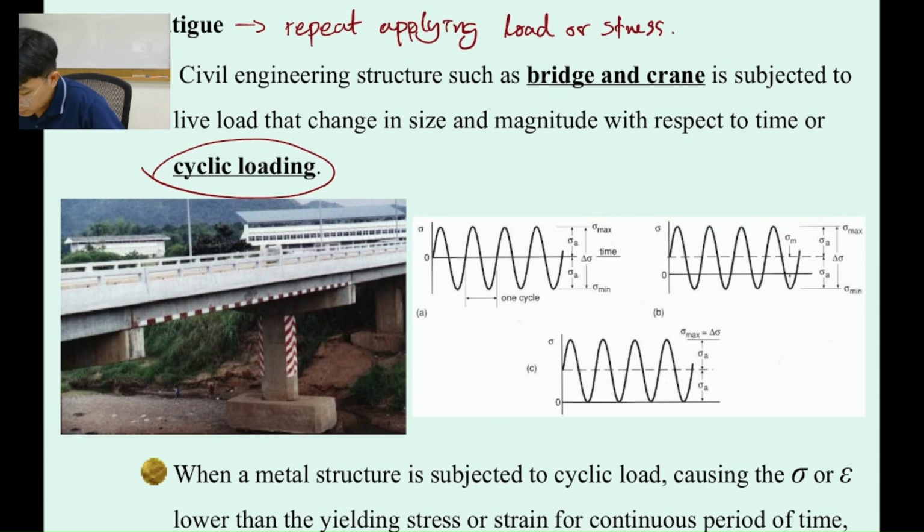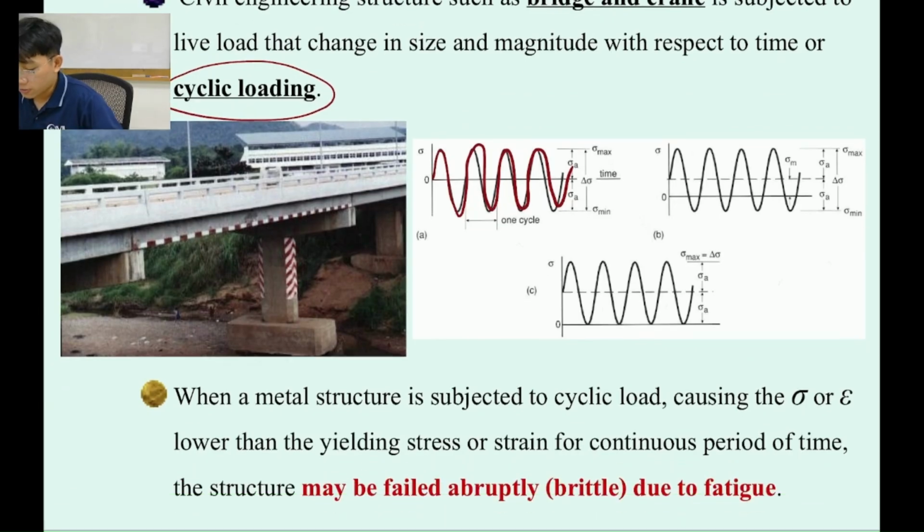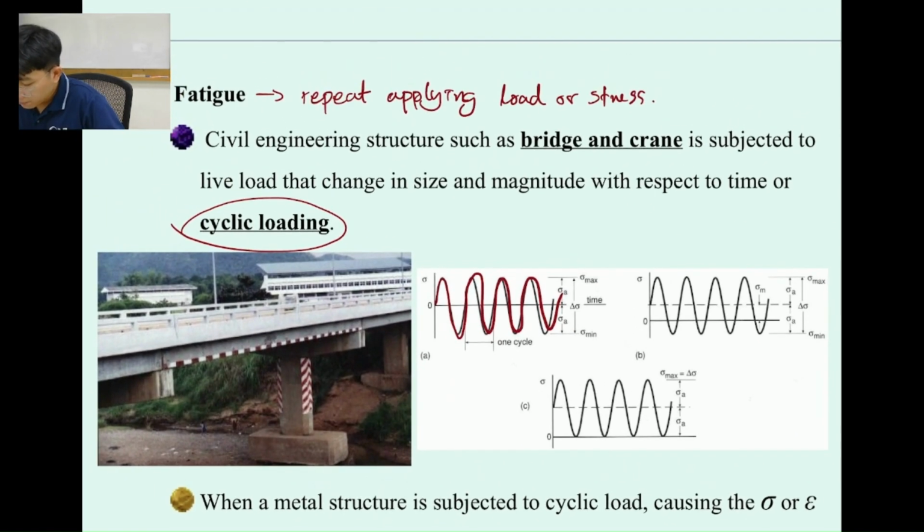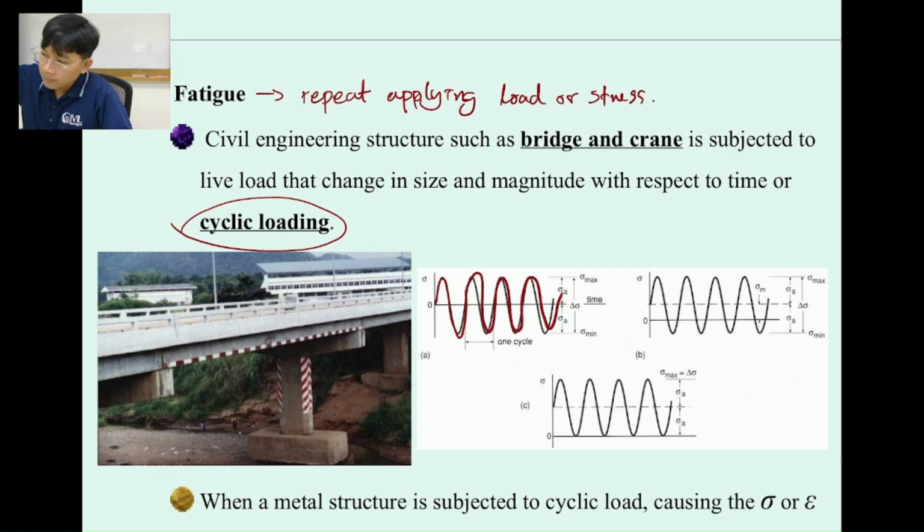So cyclic loading means you apply the force, release, apply the force, release in a cycle like this. Okay, and what we measure from fatigue is simulated from bridge and crane design. A crane needs to lift some equipment and then release it, so it experiences lift a load, release, lift, release. It's similar to a bridge.